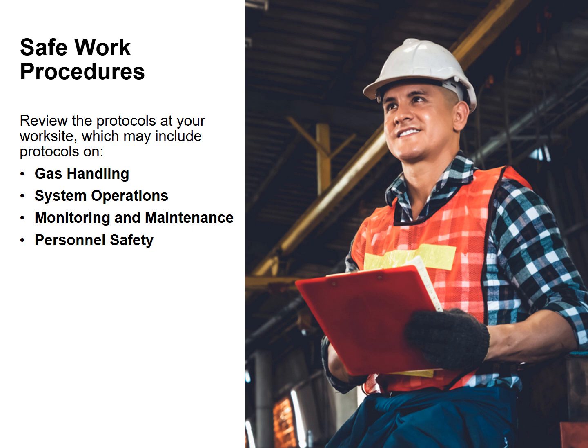These procedures provide standardized instructions for the safe handling of toxic process gases and are essential for maintaining a secure work environment. Review the protocols at your worksite. Common procedures may include gas handling instructions, system startups and shutdowns, monitoring and maintenance for equipment, and leak detection and safety protocols for lone work. Understanding and implementing these procedures is a fundamental requirement for operational safety.